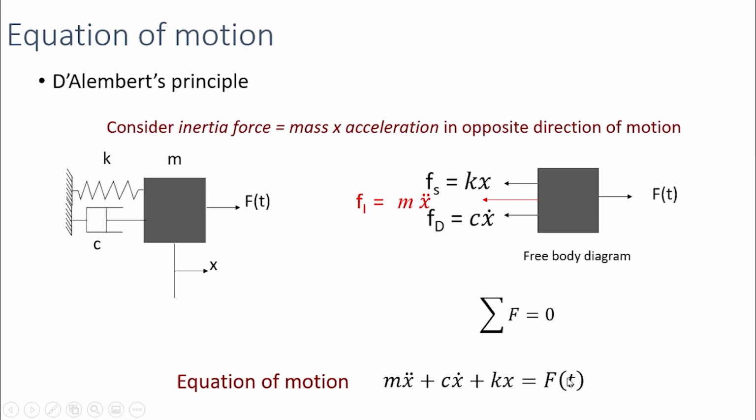Now we have made the mathematical model of a single degree of freedom system. Now we need to solve it. We can solve this equation for various types of forces and get the behavior of structures under those dynamic forces.